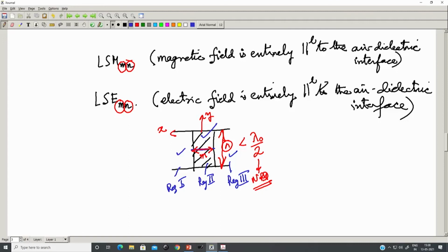Because of this, leakage and radiation losses at curved sections or discontinuities are almost non-existent in the NRD. This is a very important point to note, that this is the principal cause of the low loss and low leakage properties of the NRD.